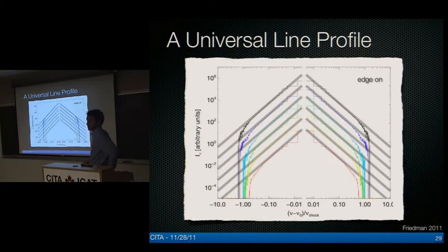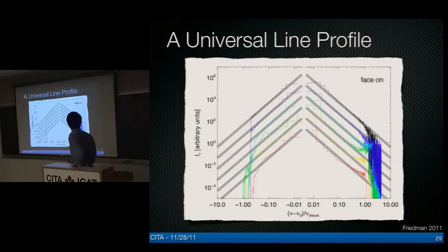And they're self-similar, except, of course, for this cutoff, which moves in for higher Mach numbers. This is with respect to the width you would get for that shock. So this delta ν^-2 profile seems to be a universal profile for the vortex field generated in a shock-bubble interaction. And you can understand that as an expression of the velocity field by looking at the velocity field.